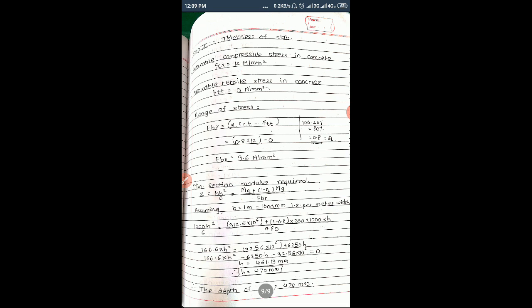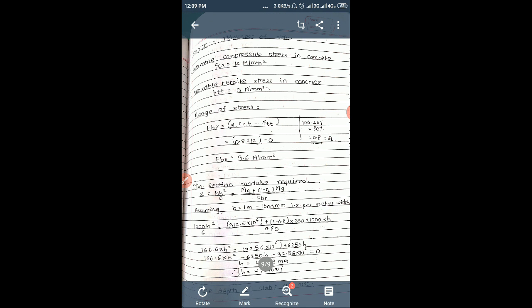So we'll get the value in terms of B and H. It is Mg equals 0.3 B into H Newton meter. You can keep units in kilonewton meter. We will use this value in the calculation of thickness of slab, that's why we have taken it as kilonewton meter. You can convert there also, or you can convert here also.